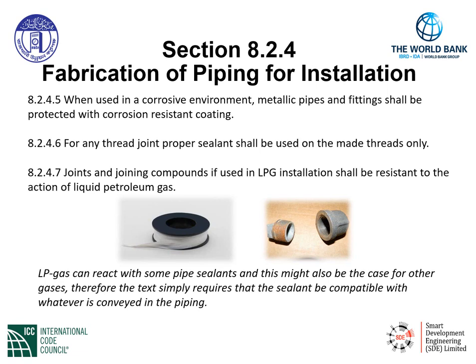It's up to the designer to properly specify what type of joining methods, compounds may be used in that type of system. LP gas can react with some pipe sealants. This also may be the case for other gases as well. Therefore, the text simply requires that the sealant be compatible with whatever is conveyed in the piping.